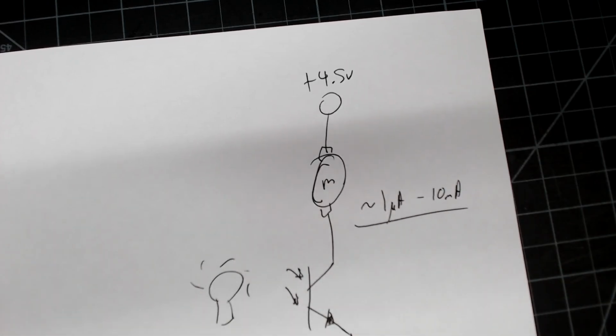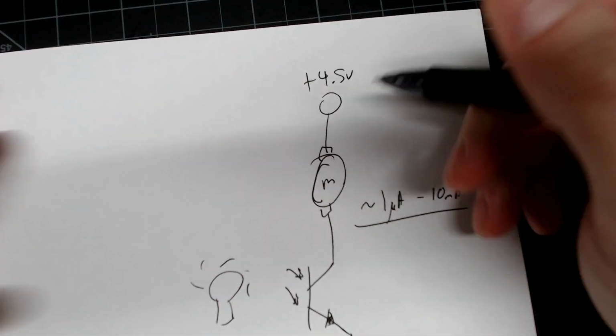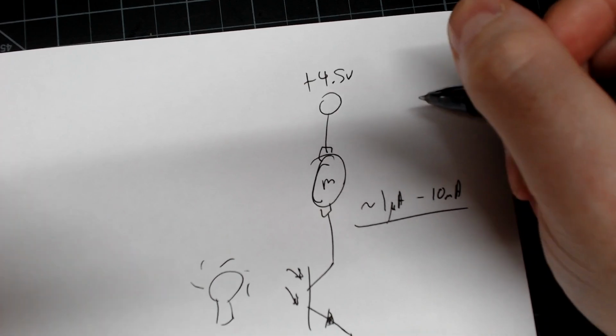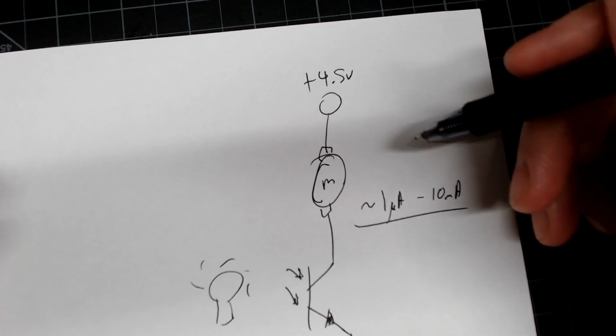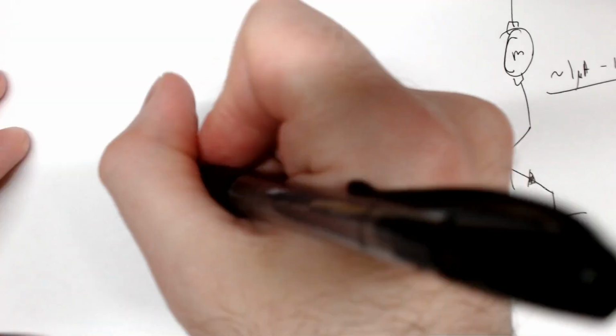Overcoming the static friction of these physical brushes that are moving around. That takes a bit of extra juice, and then it starts stabilizing, and it can drop down to as low as 90 milliamps or so, even a bit lower. So this can't actually source it, and that's true in a lot of things.